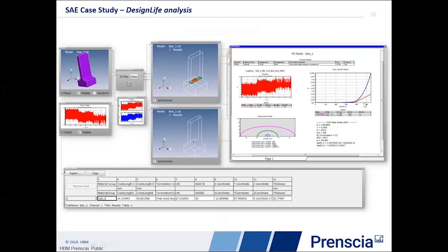And in this particular flow that we put together, we created a report, and coming out of this were things such as the structural stress history going into the component, and things such as the growth curves. The red curve is the growth through the part. The blue curve is the growth of the crack as it widened out.